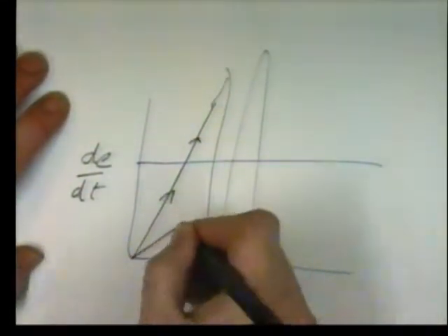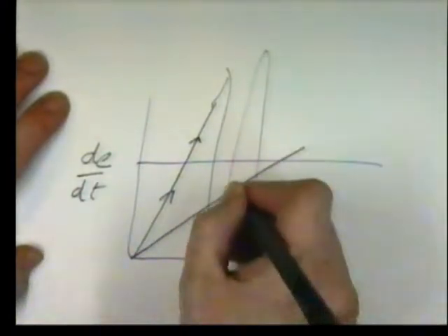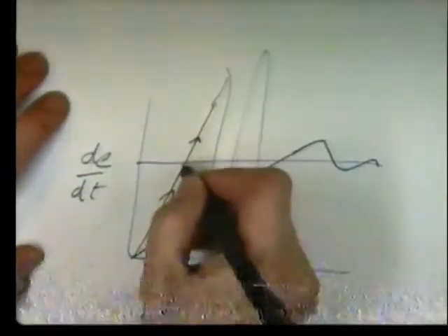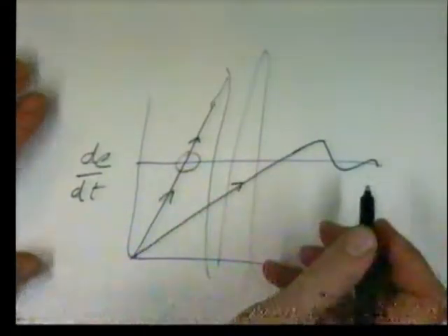Because if we had a response that was doing that, a much lower rate of change, we're more likely to come under control. So if we measure the rate of change of our error signal, if it's too great, we know we should be closing our valve off because we're in danger of accelerating through the set point. And so we have what is known as the derivative term.